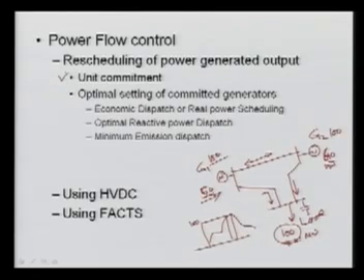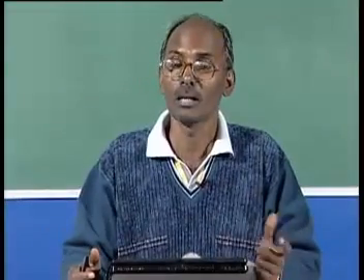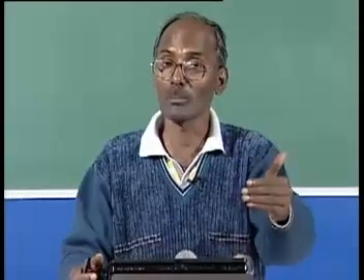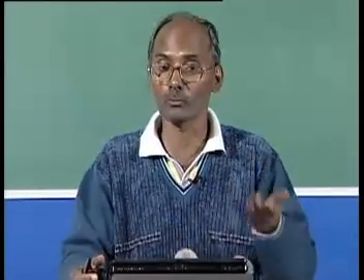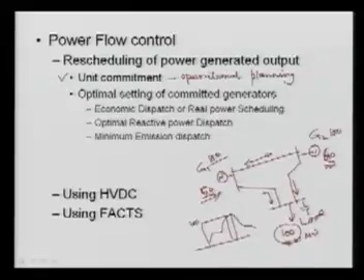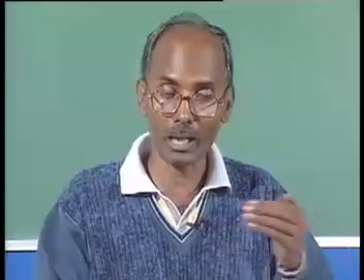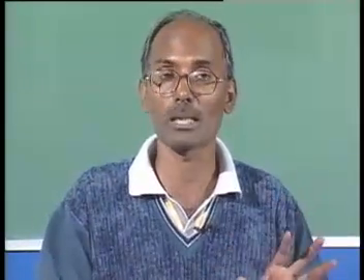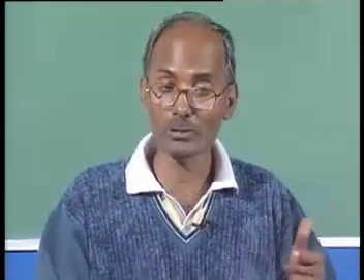This unit commitment problem is nothing but an operational planning problem. It is related to operation, and it is planning. So we have to plan which unit will be on and which unit will be off. That is called commitment. Commitment means which unit will come on at what time, and which will go down, which will be shut off at what time. This is called your unit commitment problem. And again, our criterion is that we have to commit or decommit the units based on the minimum cost.